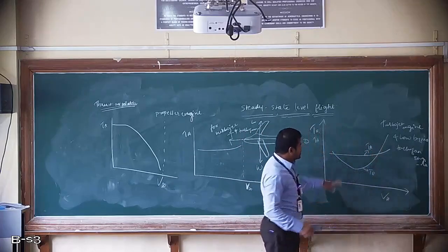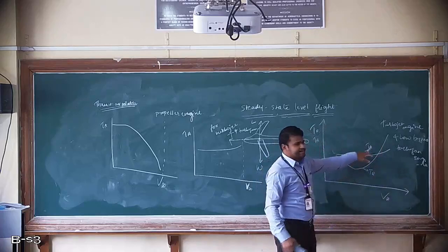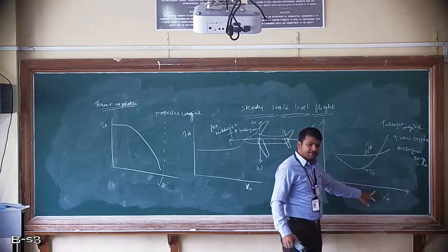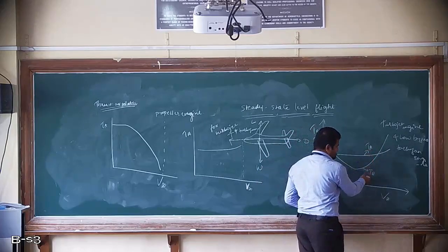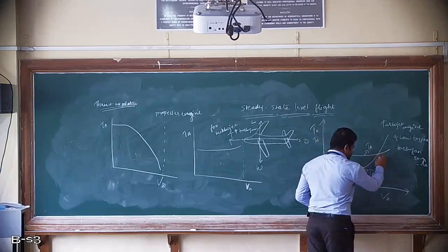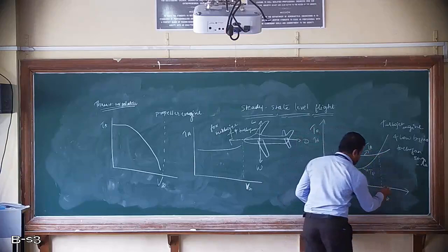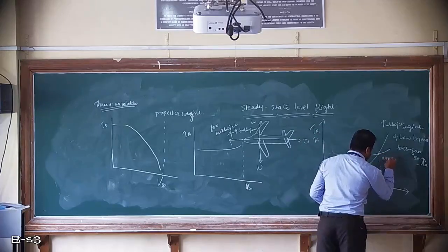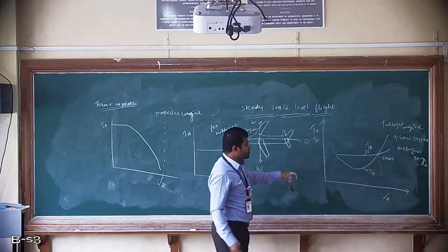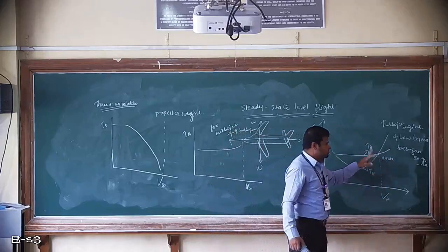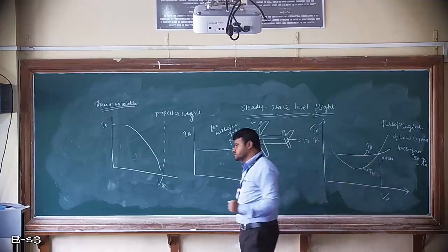So now, imposing both, where these are intersecting at higher airspeed, where the thrust available curve and the thrust required curve intersect, this point is called the maximum velocity point. So we can say the Vmax point. This is the graphical approach to find out the maximum velocity point using the thrust available and thrust required curves.